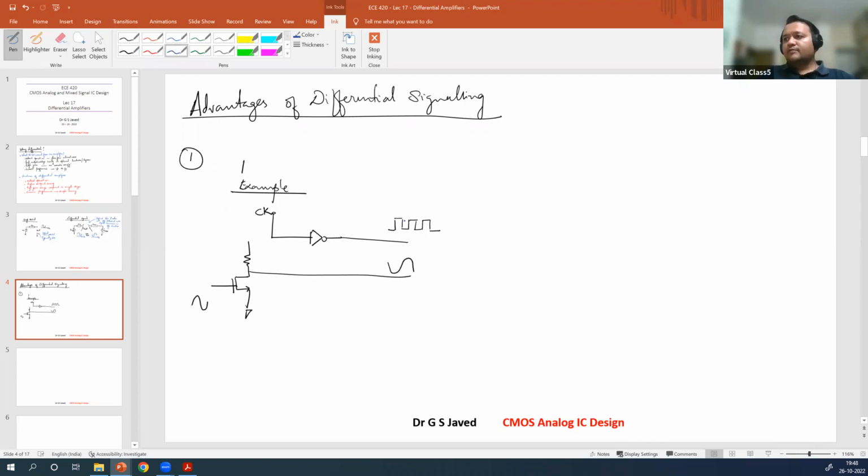But you can also see that every time there is a peak signal, you will also see peak graphs like this. Right? So this is called noise. This is the switching noise, switching noise of a clock, or it is also called coupling, signal coupling.